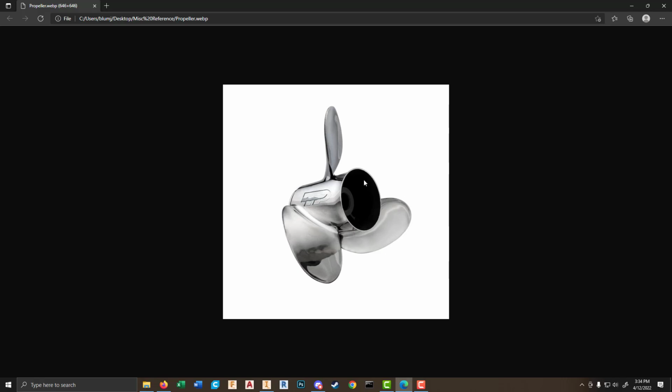And you might say, well, Josh, that's 4 parts, right? There are 3 blades. In Inventor thinking, though, I'm looking at this and I'm thinking, these are identical blades. I'm going to make one of them, and then I'm going to make a circular pattern to get the others. So it is one blade that I've patterned around.